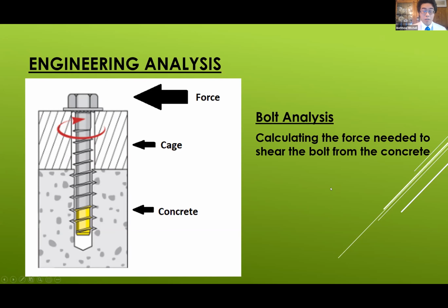Another interesting thing I'd like to mention is that the next form of failure that will occur is edge shearing at the mounting hole. What edge shearing is, is that instead of the hole oblonging, the mounting surface itself will shear from the hole like a crack, and a small chunk of the cage will break off, meaning the cage will no longer be attached. This occurs at 2.62 kips of load. So basically, the cage will break first before the bolts do.